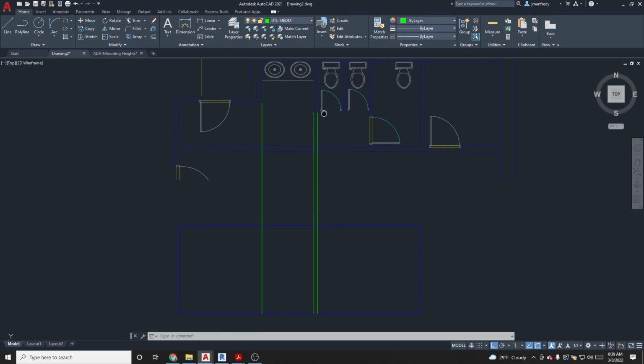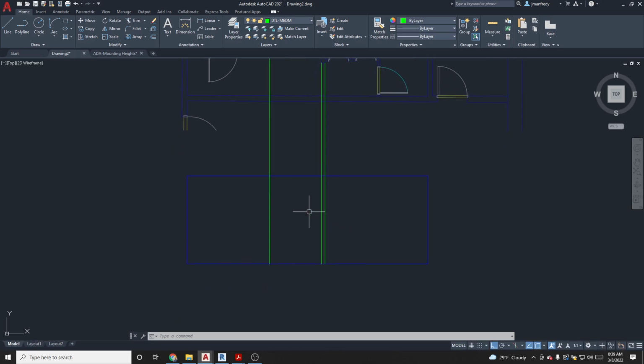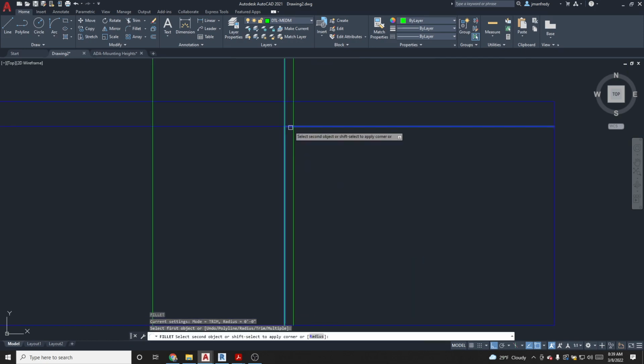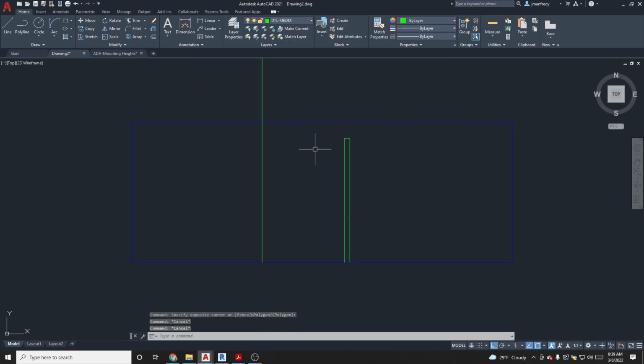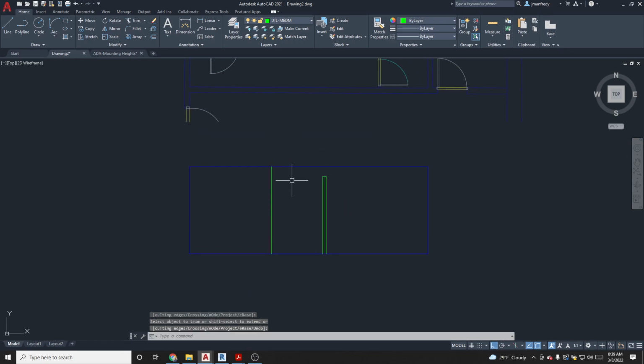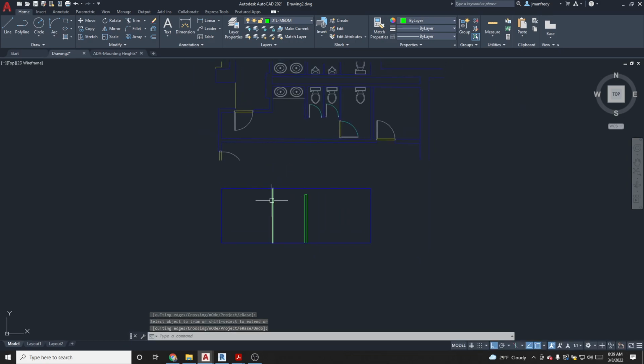This wall here next to that laboratory there is not 9 feet tall according to the drawing, so we're going to cut it off at, let's say, 8 feet. So 8 feet offset here will allow me to cut off this wall. We'll fill it, and then all those layers there will become detail medium. Trim here, TR for trim, will cut off that line there.